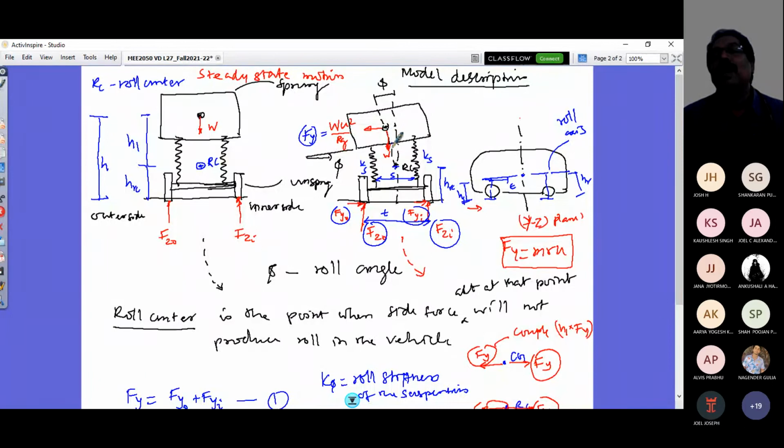and instead we will look at now the roll moment along with that, considering the whole body, considering the roll axis. At that time we will consider that. In this diagram, the moment is not considered because this angle is a very small angle, and this distance is h1 sine phi, and sine phi here is going to be phi itself, very small, and that is neglected. That moment is neglected. That's why in the Gillespie textbook, this W is not shown in the diagram itself, right?